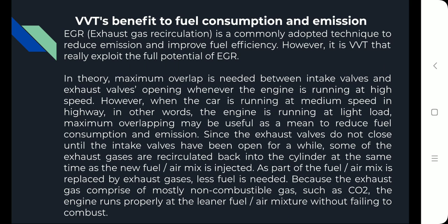In theory, maximum overlap is needed between intake valve and exhaust valve opening whenever the engine is running at high speed. However, when a car is running at medium speed on a highway, in other words, the engine is running at a light load, maximum overlapping may be useful to reduce fuel consumption